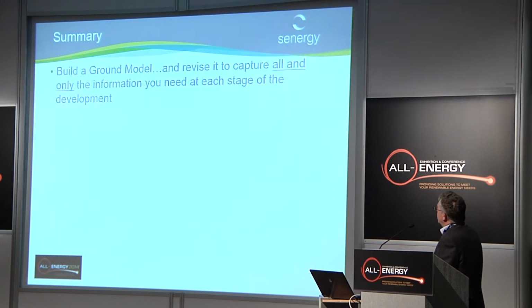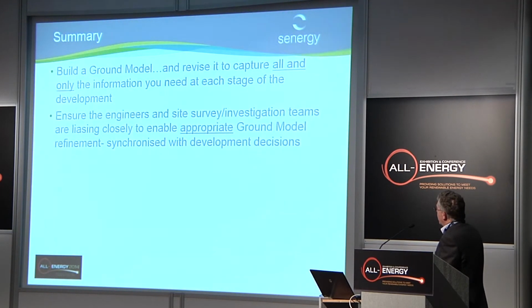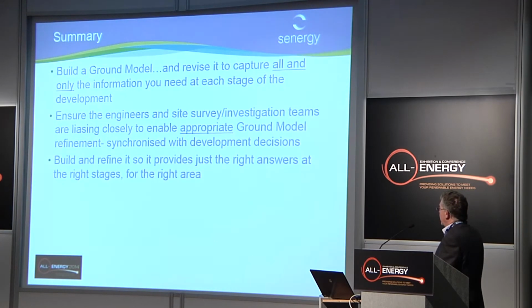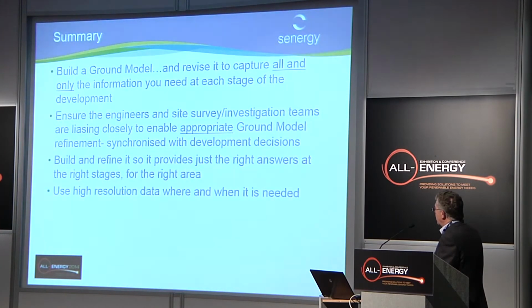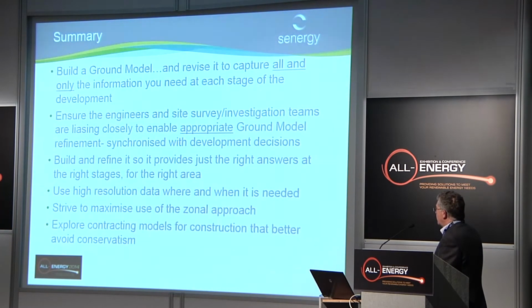So to summarize, we must build a ground model to do this work. We must revise it to capture all and only the information that you need at each stage. Make sure that you're liaising with the engineers continually to enable the appropriate ground model refinement, which is then synchronized with the development decisions, and you make sure you're delivering the right answers at the right stages for the right area. Use the high-res data only where you need to. Make maximum use of this zonal approach, and explore contracting models for construction that better avoid conservatism.